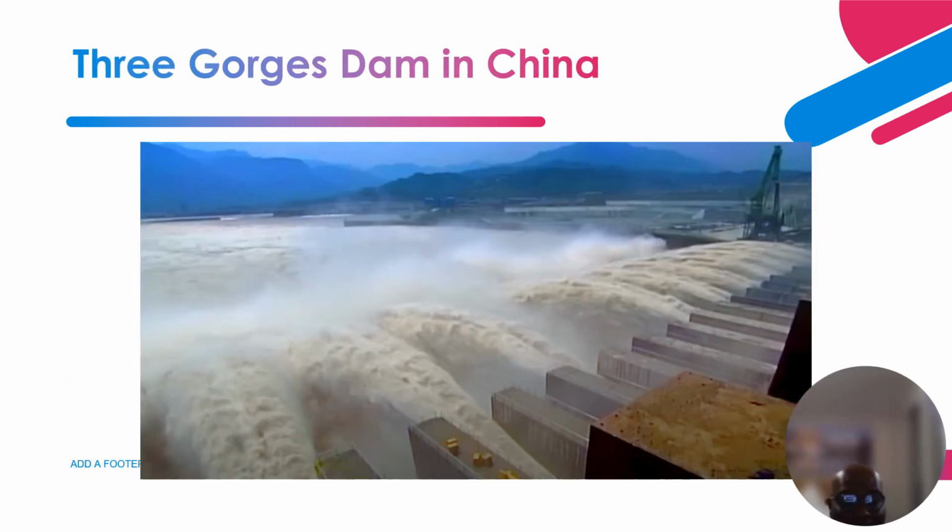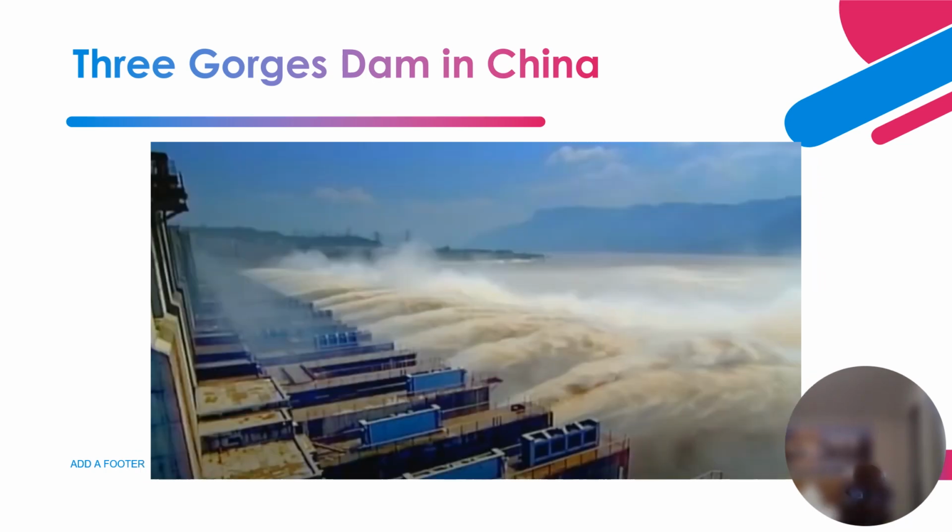So this is a picture of how they flush the sediments. Remember, I made mention in the last 2 slides how they flush the sediments out of the dam reservoir. You have sluice gates. Instead of the water going through the turbine, it goes through another gate to flush out, because this water has a lot of sediments, and you don't want that water going through the turbine, because you end up destroying and eroding the turbine blade. So it goes through another part and flushes out a lot of the sediments that have built up behind the dam. Next is another picture of flushing out the sediments from a different angle.